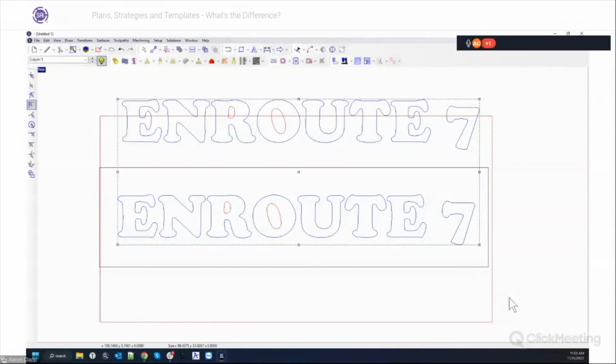Although I can also see how potentially, if you're using bridges, for example, bridges would be a really good example, because if you don't have vacuum pressure, or you need help with the vacuum, or your machine just doesn't have vacuum at all, you might use bridges, right? Well, let's say you go from cutting a 1 inch piece of material and your bridges work great, then you go to a half inch, your bridges are going to get cut off, because your bridges are typically towards the bottom. And if your bridges are being placed way down deep at 1 inch, and your machine is limiting the z-axis, then all of a sudden you won't have any bridges. So yes and no. It depends on what you're doing.